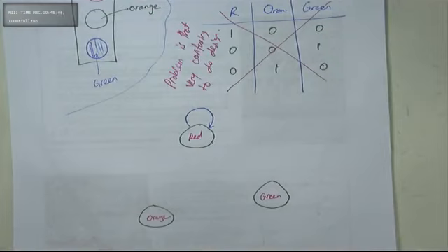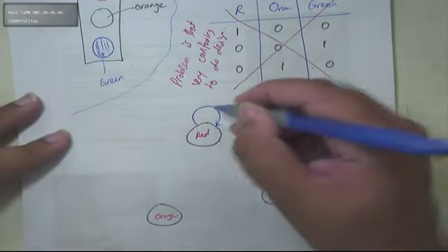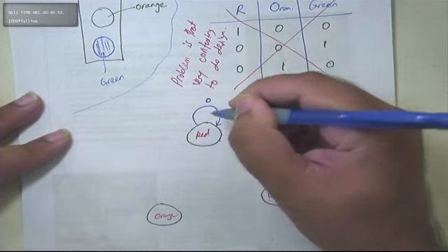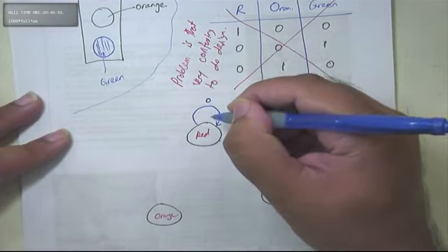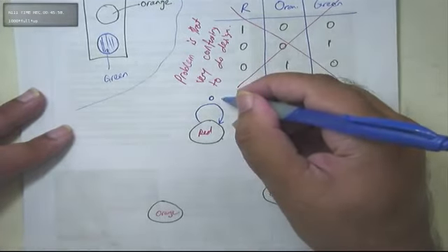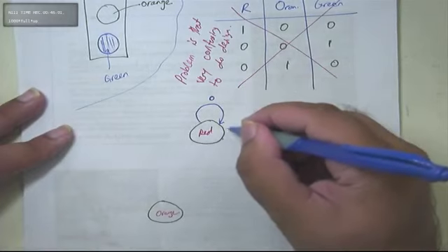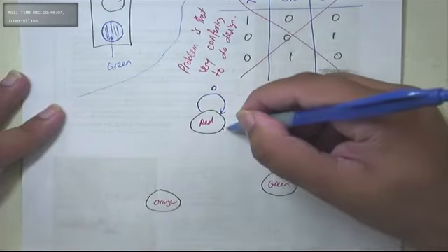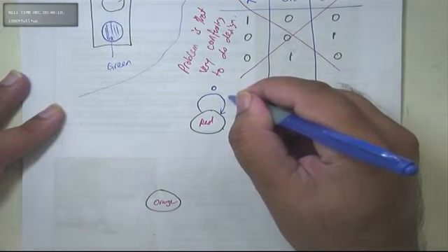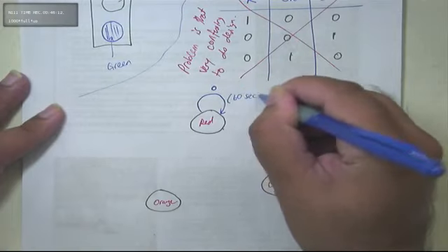Let's make it small. 60 seconds for red? Okay, so it stays here at 0, no movement. The input trigger is equal to 0, and it stays here at red. Once it gets triggered, the trigger stays for a length of 60 seconds.